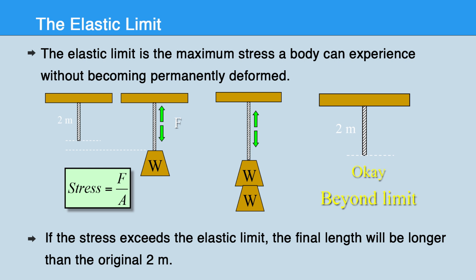There are two yield points, the upper yield point and the lower yield point. Ultimate stress point. It is the point that represents the maximum stress that a material can endure before failure. Beyond this point, failure occurs. Fracture or breaking point. It is that point on the stress strain curve at which failure of the material takes place.